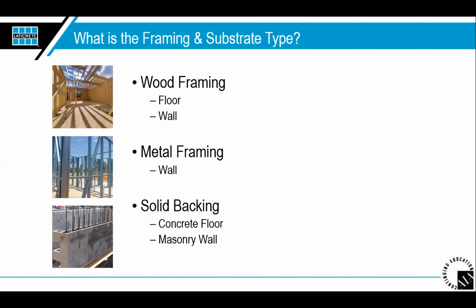And we see that commonly whenever you look at a wall, you'll notice that it's lighter, and then as you get to the bottom, maybe a couple feet, you'll notice a darker stone, or maybe a delaminated stone, because the hydrostatic pressure is actually pushing that off the wall. So many different scenarios there whenever you're talking about masonry walls.